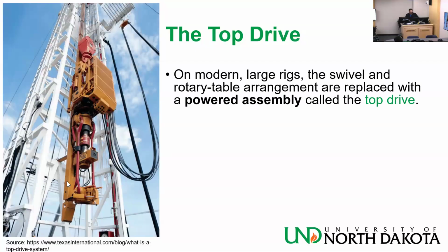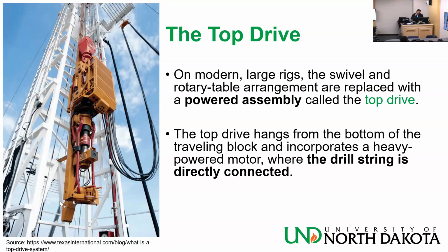On modern large rigs, the swivel and rotary table arrangement are replaced with a powered assembly called the top drive. The top drive hangs from the bottom of the traveling block and incorporates a heavy powered motor where the drill string is directly connected. No need for Kelly or Kelly bushing.